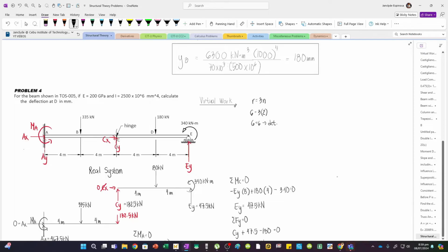So here I have the members. So we have AB, BC. I will teach you the better technique. If you have two segments and an internal hinge, the two segments should be going toward each other. So if I have AB, then my other member must be CB, so that my moment equation will only include a few loads. That's the nice part.